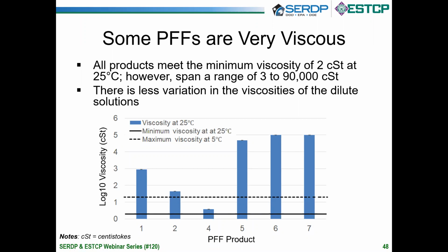And what it might do is give some problems in handling this material, because we have to blend these with water, and high viscosity requires some equipment changes at the very least. We do know that once you dilute these products, the 3% or 6% solutions for making foam, those are much more manageable, so that's not a problem, but it's the handling of the concentrate.